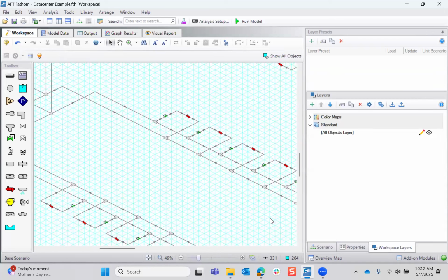The flow is being distributed to a whole bunch of different units. Originally, I said air handling units. Technically speaking, this setup would be able to work for both air handling units, or if you were doing something more like direct chip cooling, you could model these as individual racks for the flow coming into them, dissipating the heat and pulling it out the other side, effectively treating those servers as heat exchangers.